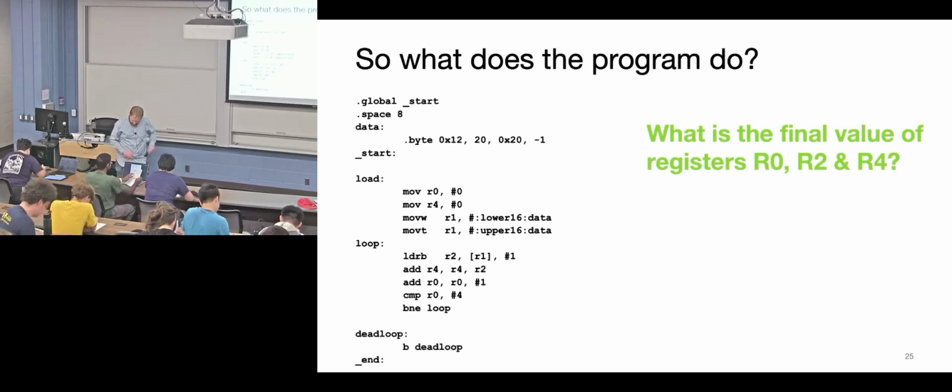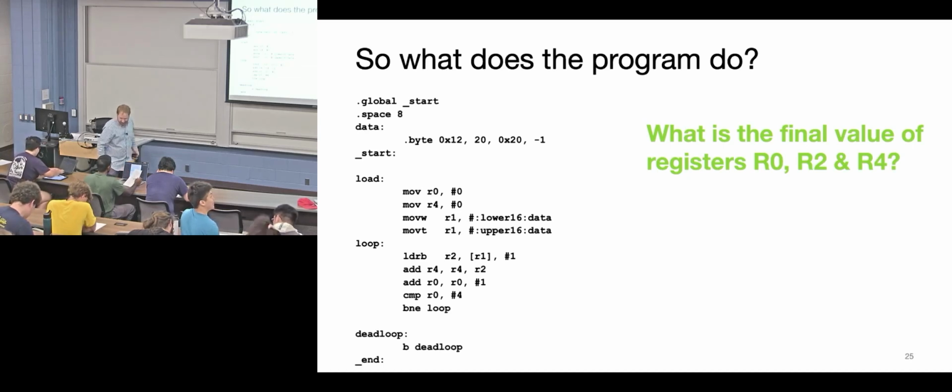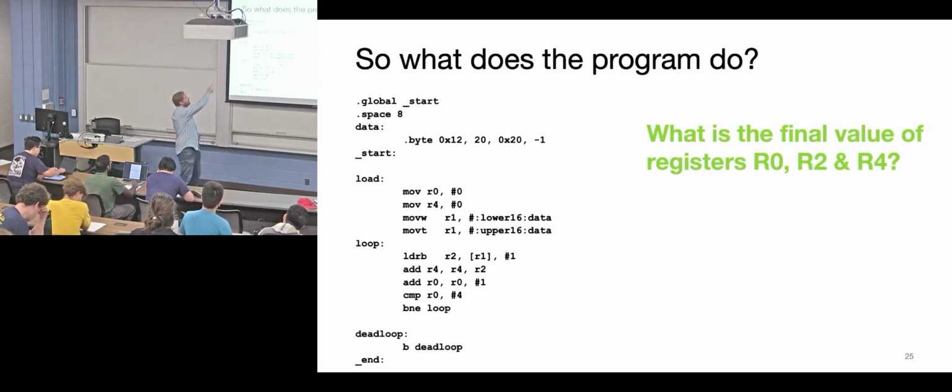I just want to make sure: by instruction, you would put 0x12 as the first byte, the next byte, and then the other values. Right, so the byte command works on each individual byte, not on the entire word. So it's equivalent to saying byte hex 12, byte hex 20, byte -1. It puts a value in one location, increments, then the next location, and the next.